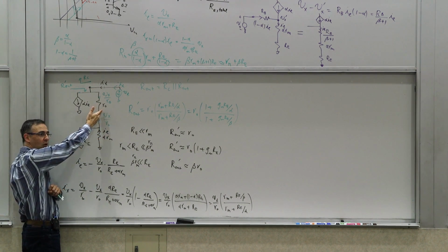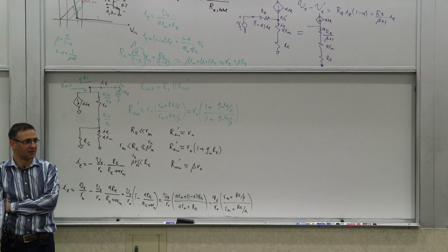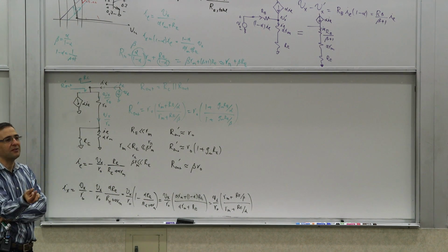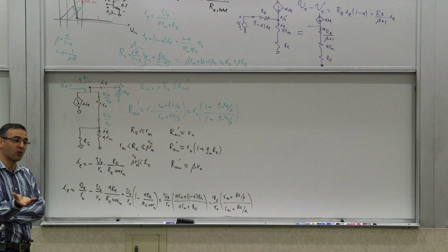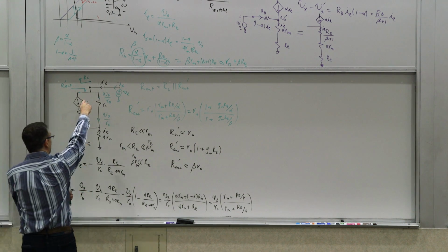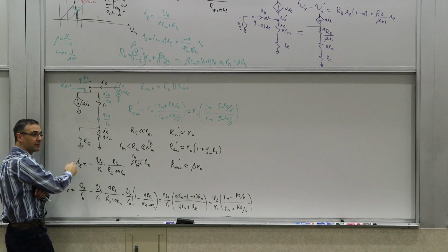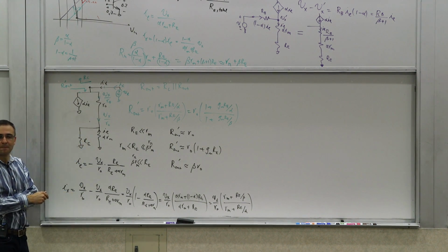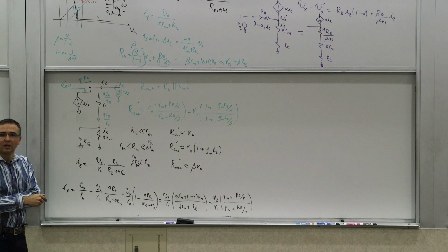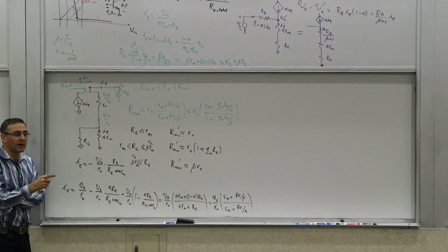So it's hundreds of kilo ohms to tens of ohms. So that doesn't matter. It's this tiny resistor in series with a large resistor. It's not going to play a role in determining the current, but it will play a role in determining how the current is divided between this one and that one. Right? Any other questions?